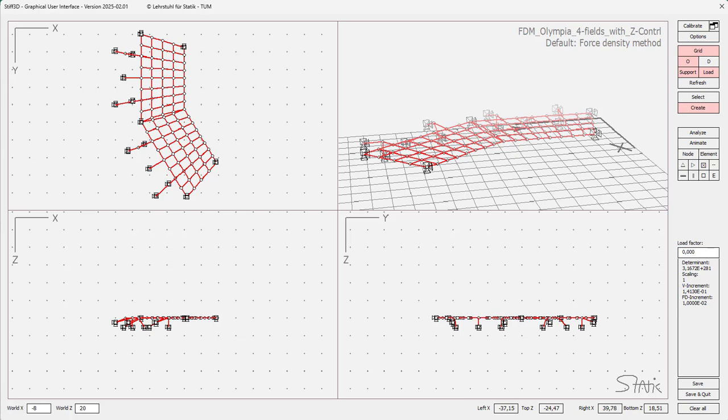It's dedicated to the point of departure of our workshop, the Olympic roof. A little bit simplified, of course, not to make it too complex. So what are we dealing with? You see from the top view the cable net with the edge cables and the surface covering cables. We will see in a moment there are posts and suspension cables. What we would like to control is the length of these posts, which will evolve just in a second, and we would like to control the z coordinate of this node.